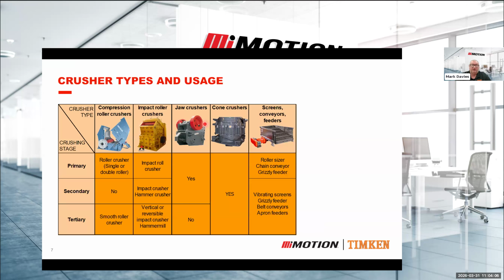The reason why they break it down into primary, secondary, and tertiary is basically to size that rock once they crush it. The output of a primary crusher, as we'll see in the next few slides, is still quite rough, and it comes in different sizes. A secondary crusher is a different type that processes that rock down into a more consistent size, and then it allows them to process it or transport it on conveyors in a much easier process.